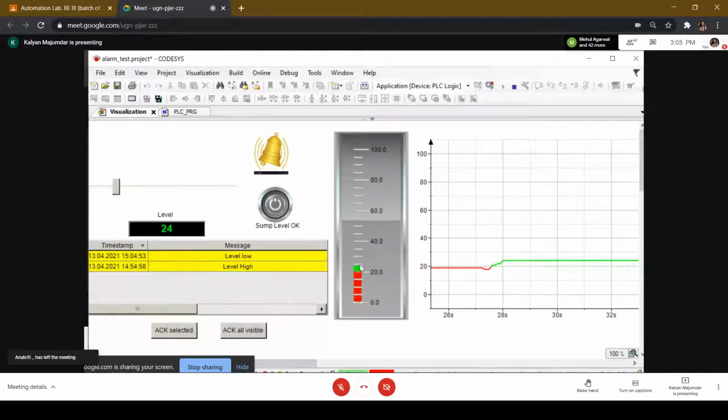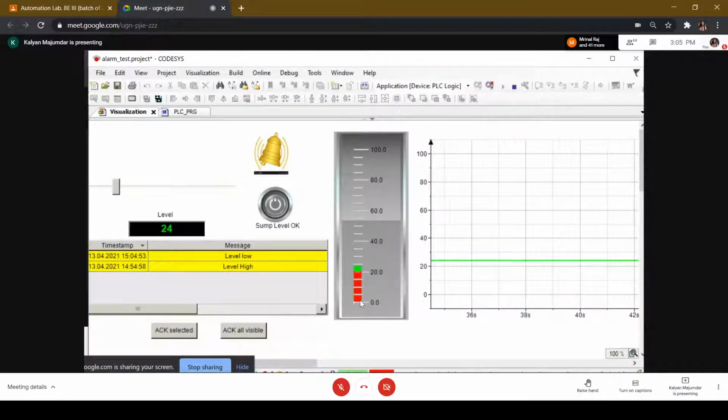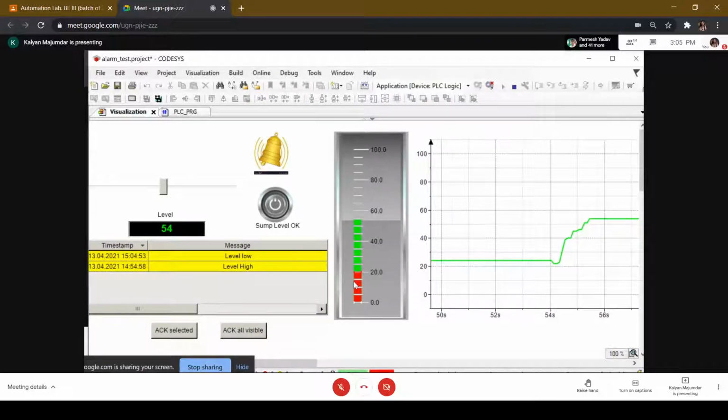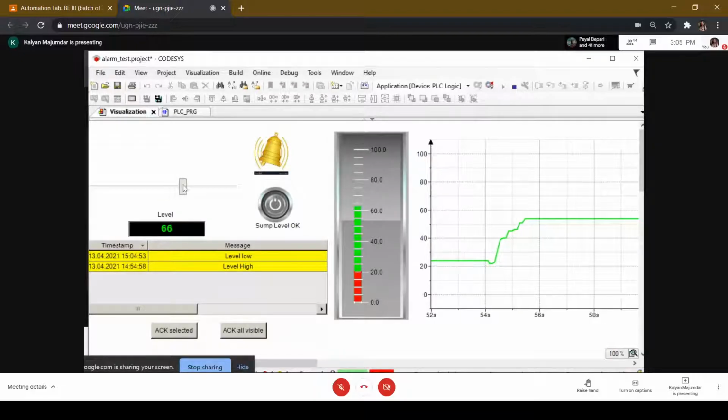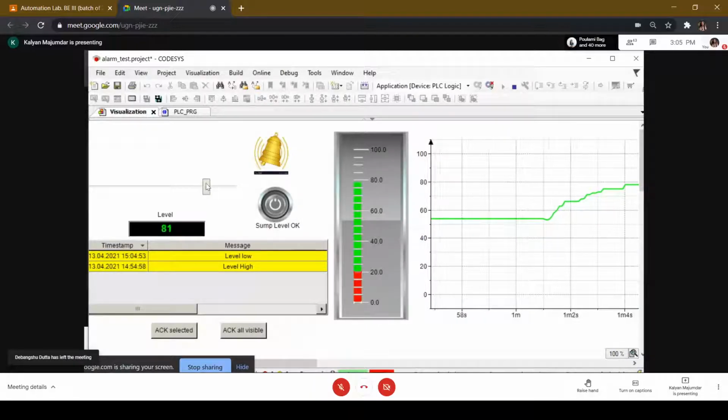Of course, in some software this is not supported, but in certain other software, what you could do is change the entire bar to green. That is, as long as the bar is below 20, it's red. The minute it crosses to a value that is greater than 20, it remains green until you get to 80. But here what happens is, up to 20, that part is red, the normal part. So the minute you see that the top of the bar is green, what it indicates is fine, your level is within acceptable ranges until it gets to 80, which is my upper limit, because that's the way I've defined it.